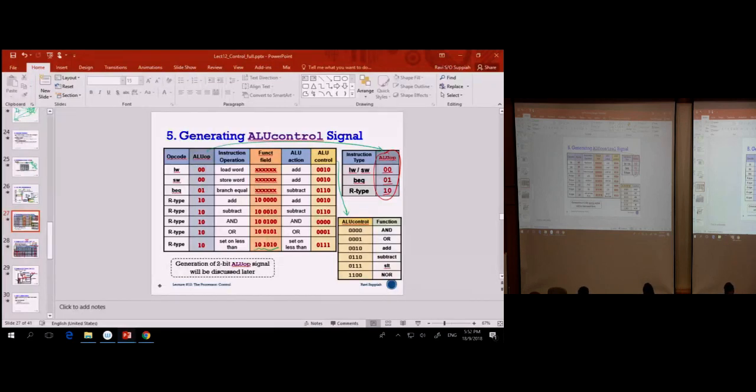So in your situation, with all zeros and all 1s, when I add the 1, it becomes 1 plus 1, 0 carry 1, then 0 carry 1, all the way, correct? So usually the answer is 0. So you're saying the last bit has a carry of 1 and it gets split to 0. That carries 1 to the next one, which causes it to flip, and all of them flip accordingly. The very last carry you can use to check whether there is an overflow condition. But the answer will be correct.